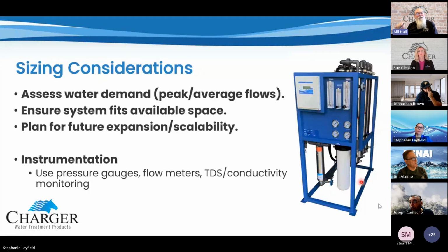If it's quit working, it's probably something that's operator error. Somebody crapped out that membrane. If you've got data that you can show them that says, no, look, I've got this, and this, now you've got a better chance of getting warranty on those membranes. Just something that I've run into in the past, and something that can help keep you out of trouble, maybe.